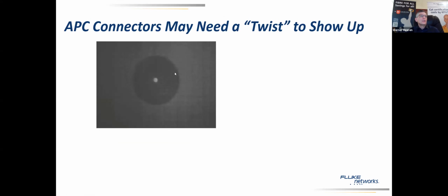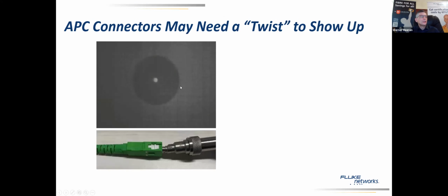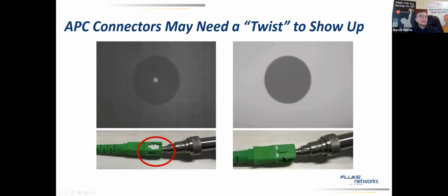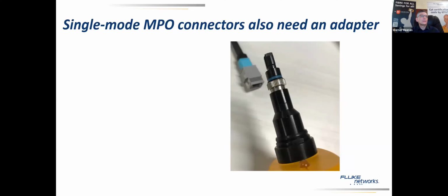Here's an example of fiber inspection, and maybe it's not very clear to look at it. So you have to twist it a little bit, and there is this indicator on the connector which should be aligned with your fiber inspection head to make you see now a better lighting on looking at your fiber surface and make the right decision, or let it do an automated decision to decide if it's a good pass or fail fiber connection.